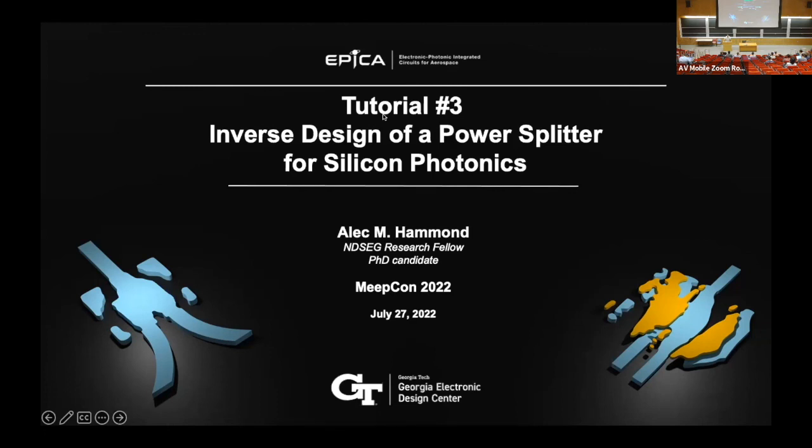This is from Simon. Beyond geometry robustness, are there considerations for materials optical constant robustness? How well is, for example, the polysilicon refractive index characterized on that optimization on the right? Great question. Yeah, so this is where you could kind of augment your robust optimization, where you don't just consider geometric perturbations, but also material perturbations. In your case, you're saying, well, maybe the refractive index is changing because the fab's not perfect. Alternatively, you could say that your device is operating in a highly fluctuating environment where the temperature is changing. That also changes the refractive index.